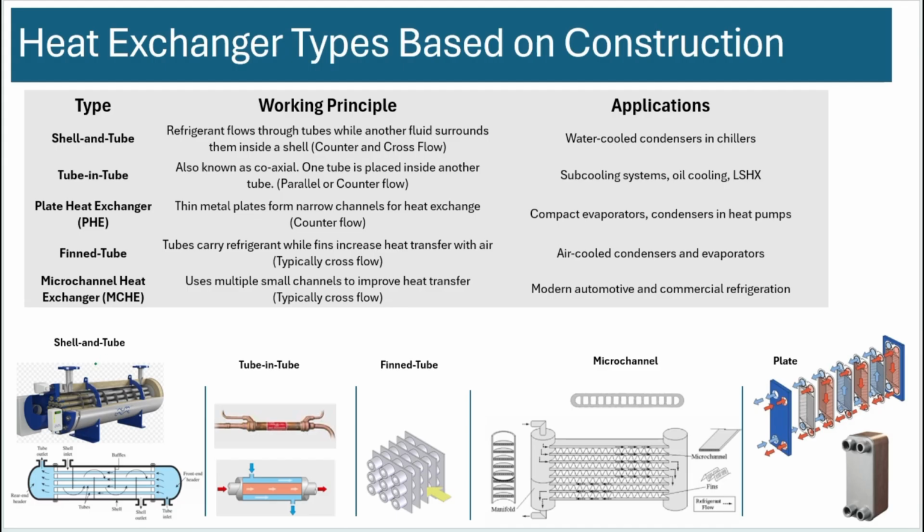By the way, you could have cross flow here. If you look at the direction of the refrigerant flowing, the fluid in the shell will flow cross to the main fluid and also counter. So it's a combination of counter and cross flow that happens in shell and tube.